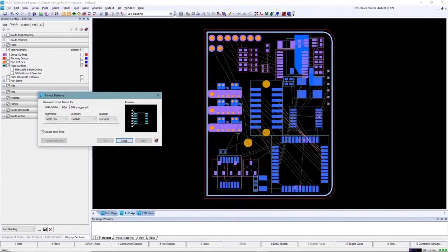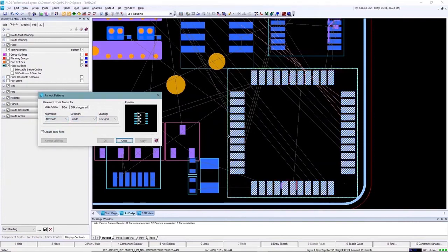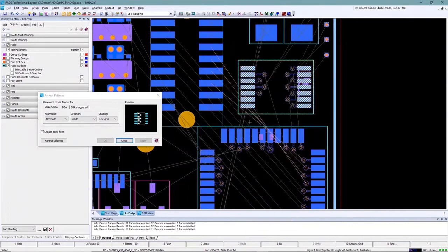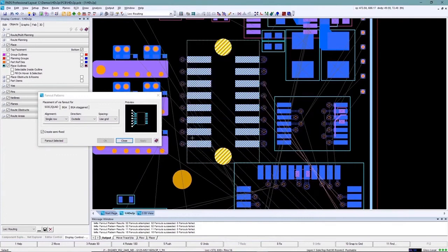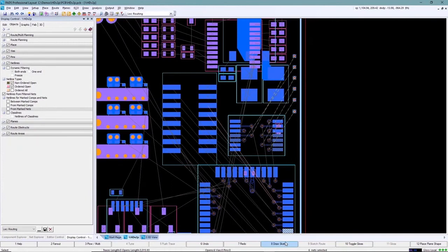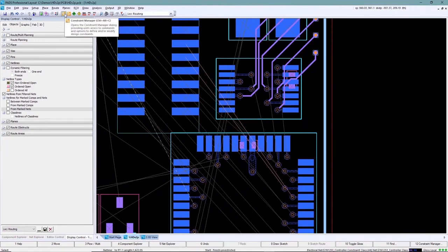Again, to facilitate faster design, I'm going to use routing automation capability in PADS Professional. To start out, I'm going to fan out a couple components so that I don't have to do this manually. After completing this process, let's go ahead and start routing. Using PADS Professional sketch routing technology, we can quickly route nets that would otherwise take 3 to 5 times as long to route by hand. As you've just seen, I routed 6 nets in about 1 second.